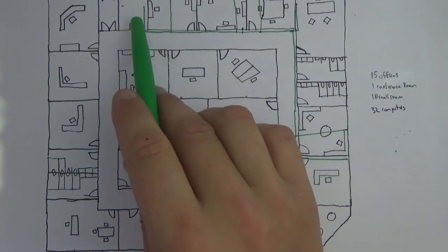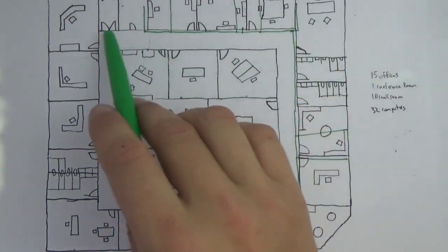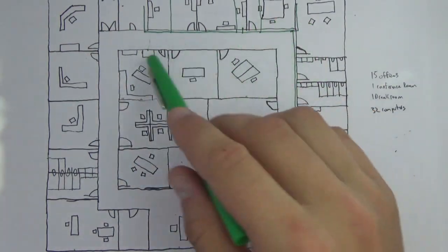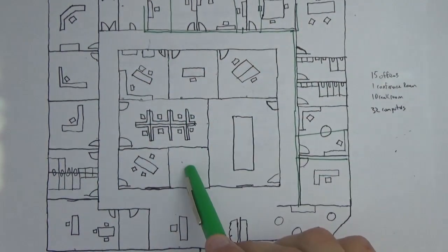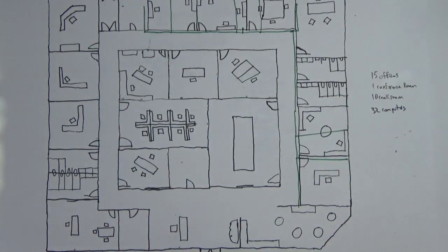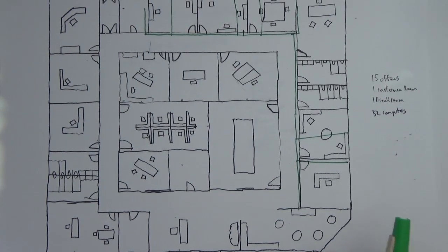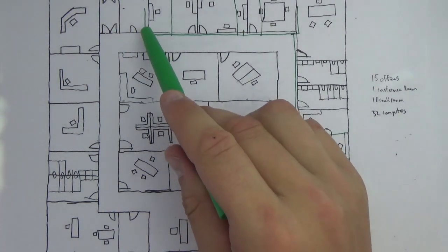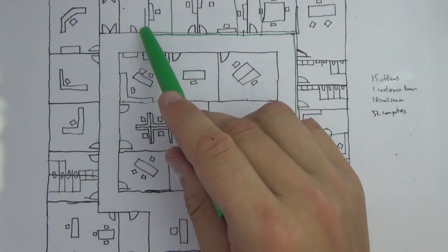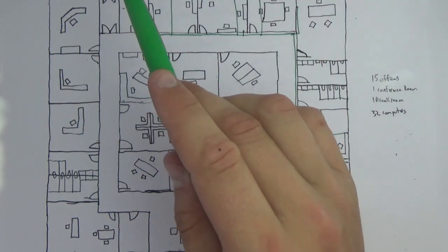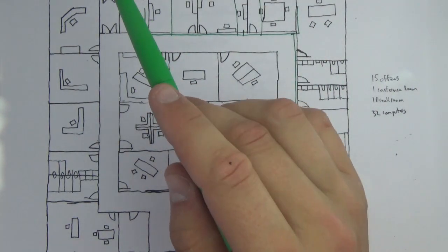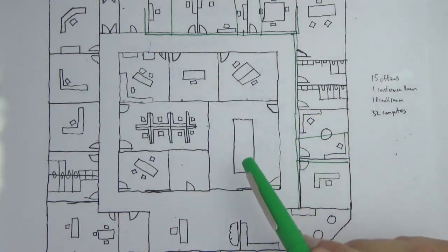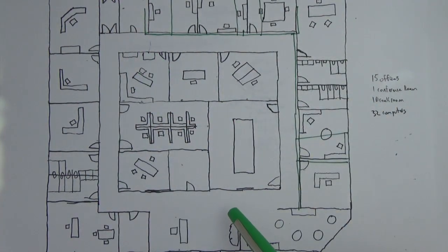Okay. So the cabling from a telecom room out to the endpoint offices, we call this horizontal cabling. A connection from one comm room to another comm room, we call vertical cabling. That term comes from thinking about an office building with multiple floors. Each floor is probably going to have its own telecommunication room. So the horizontal cabling from that telecommunication room would be all the connections on that floor, and then the vertical connection would go to the floor above it to the next communications room. It works in a two-dimensional or a single-story plan as well. It's still going to be vertical cabling from comm room to comm room.